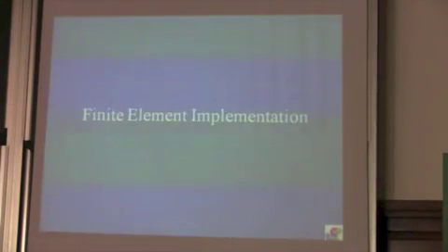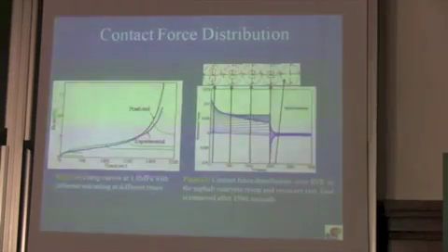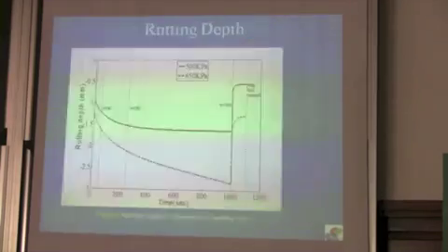Okay. All right, so I think I'm about done with time, right? A few minutes. Okay, so we will go through this. We can implement this type of model in finite elements. The only reason I show this is there's a non-standard implementation. So you cannot just take this model and put it into Abaqus or Adina. There is an additional term that shows up that has to be treated a little bit differently. So it's a non-trivial implementation into Abaqus, or you can write your own finite element program. But you end up with the finite element program. And I think I pressed a wrong button, so I need to go up.